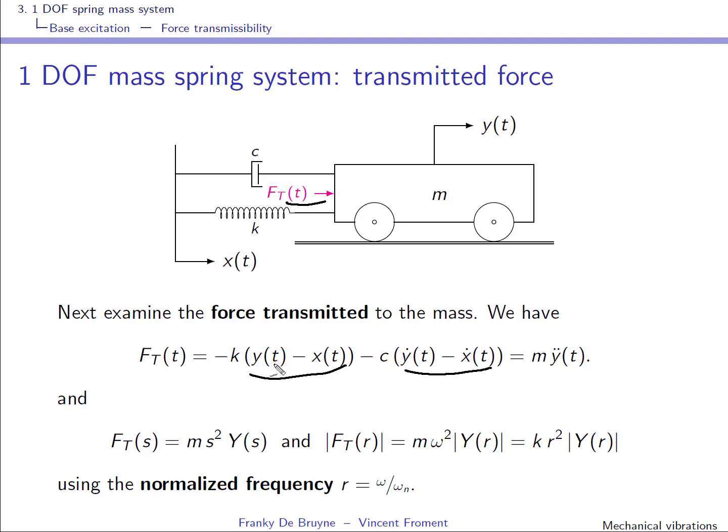The restoring force coming from the spring, and from the equation of motion that we've written previously, we know that it's equal to m y double dot. So this is in the time domain. If we go to the Laplace domain, we can write that the transmitted force is the displacement times m times s square. You see here the double derivative.